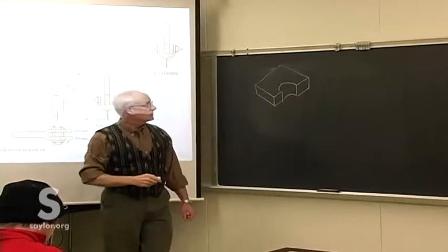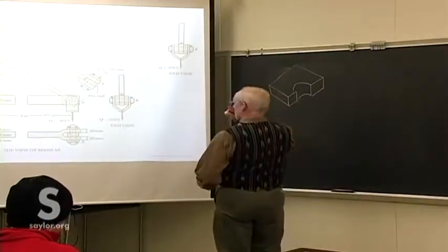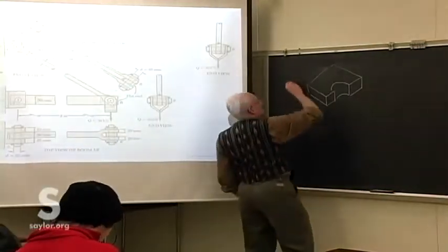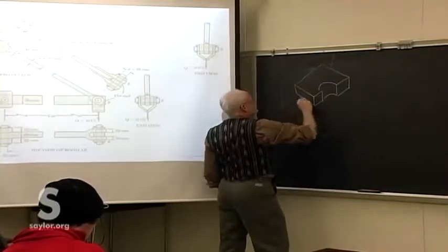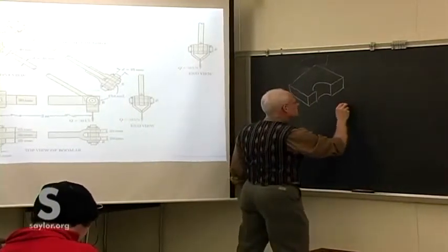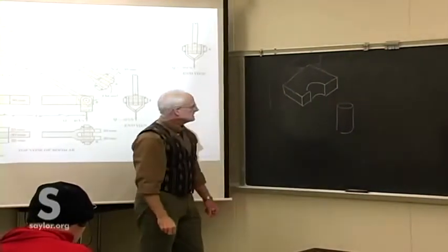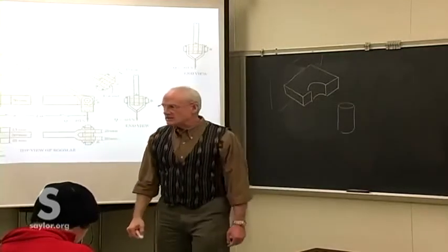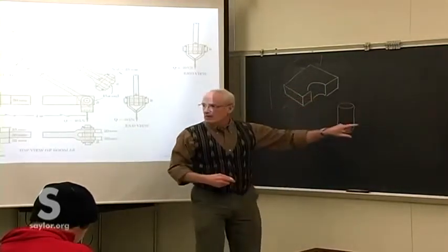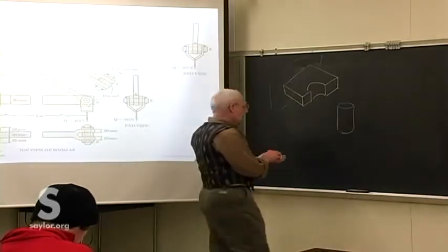this course is wonderful for your drawing skills, so I hope they're up to speed. So there's a little bit of the cross-sectional view of the bracket. Then here is the wall to which it's attached, and then the pin itself, pin A, is in the hole that I have represented here, and then the member AB is in compression, so pressing on this pin A.